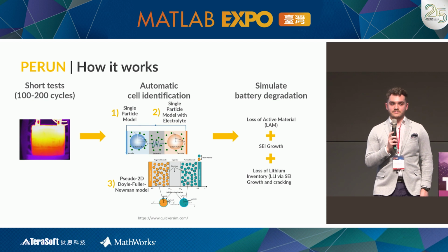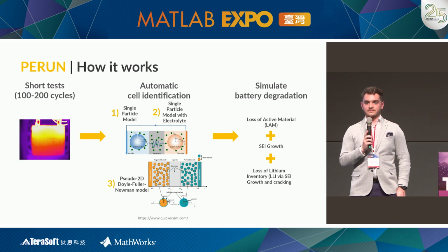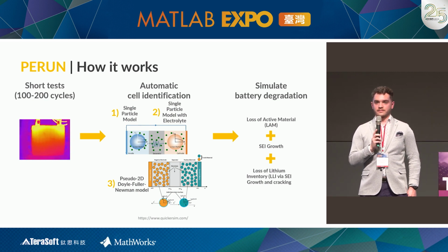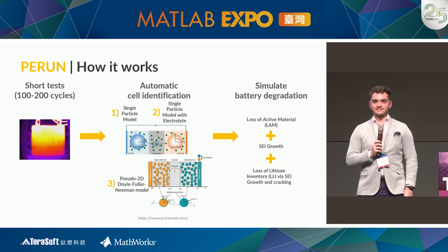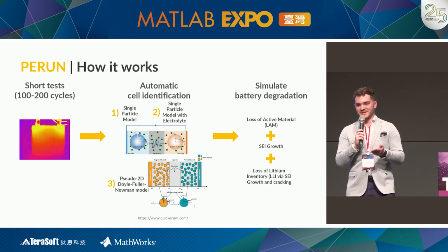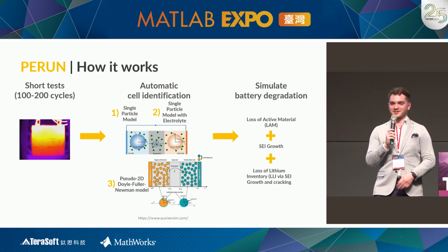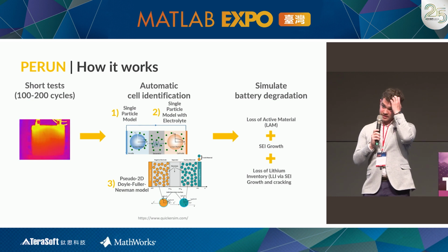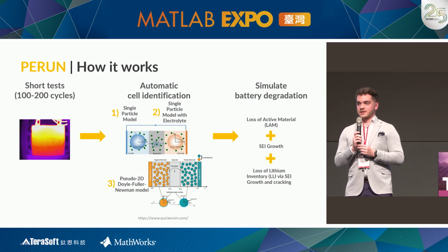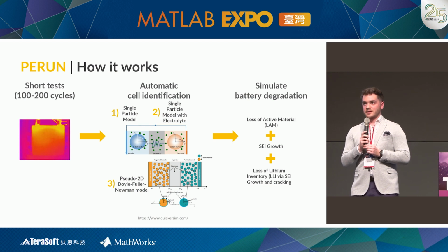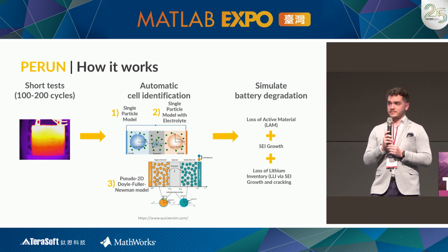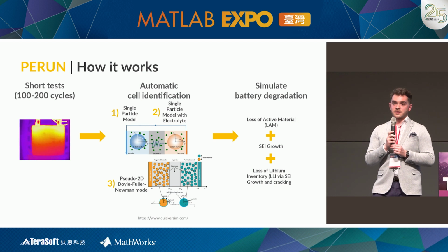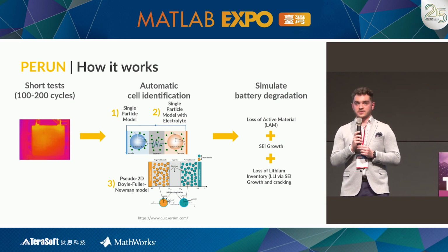Yes, I fully agree with you because you mentioned the transient response of the battery. We always keep the steady state for the simulation. For steady state, a coarse mesh is just fine. But if you want to make a transient case, I can tell you about one of the customer projects we did, for a company which makes battery packs for motorcycles.